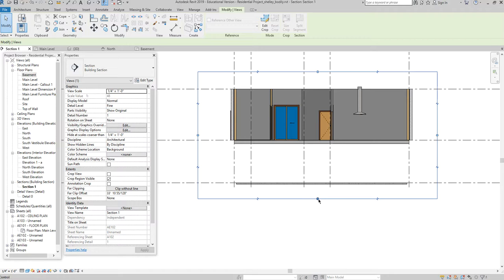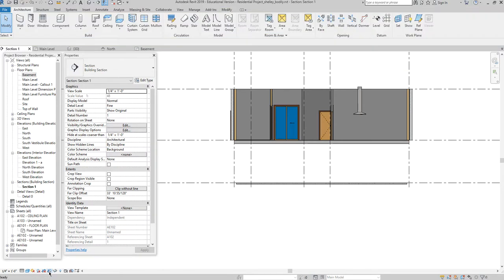Rebecca, that might be what is happening too. Maybe your crop boundary is not engaging it. Sometimes that happens. That happens with elevations a lot. If the boundary doesn't go down to that level, the elevation won't work sometimes.